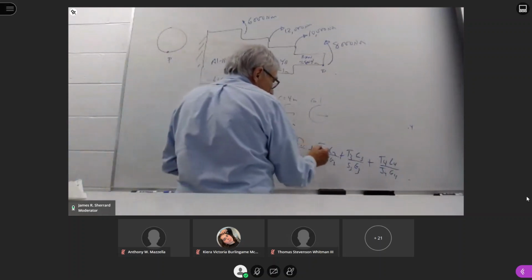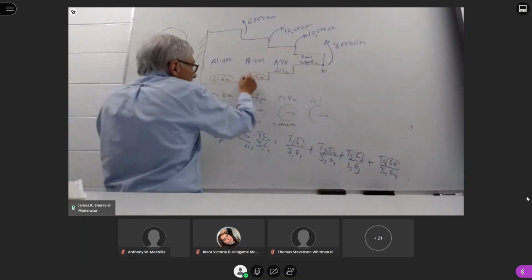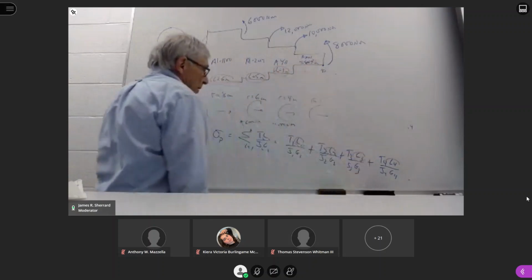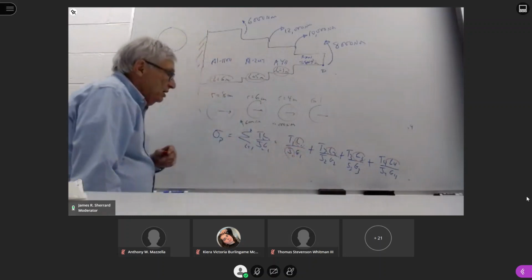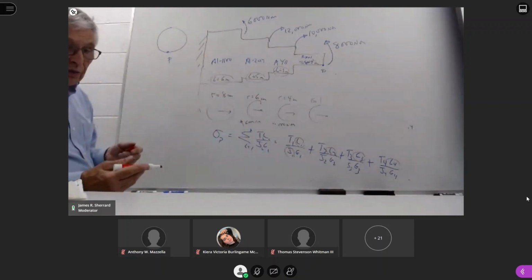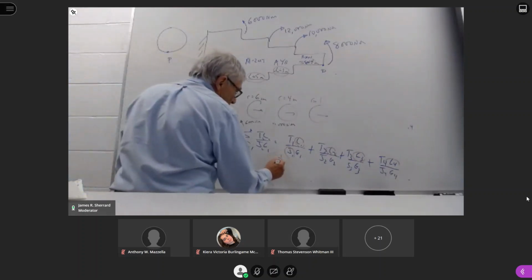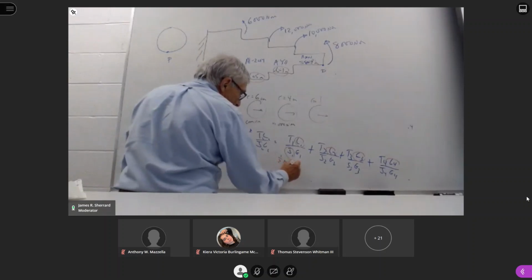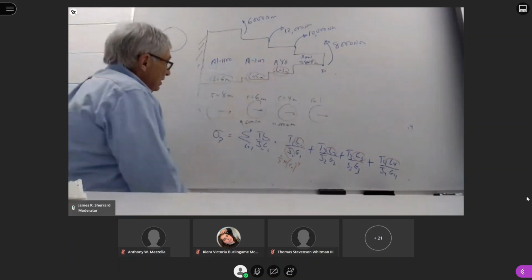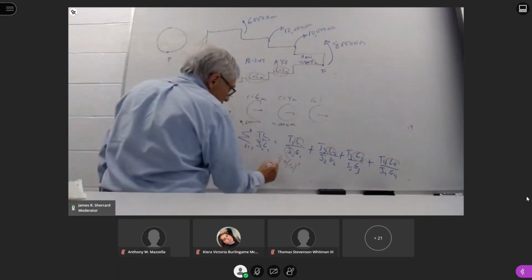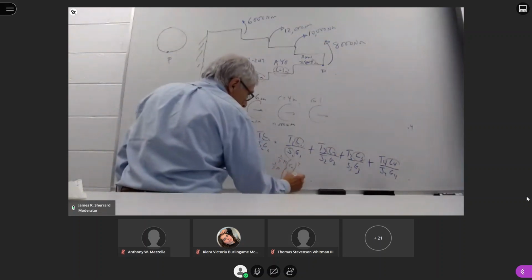The L's, we will find those values by coming back to our original sketch: Ln1, Ln2, Ln3, Ln4, respectively. For J, we go back, and this is the polar moment of inertia, which is unique to each cross-section. In each case, it is 1/2 pi times r outer raised to the 4th power. We don't have any with holes in them for hollow pipes. So each one of these, if I just look at the first one, it's going to be 1/2 pi times 8 times 10 to the minus 2 raised to the 4th.